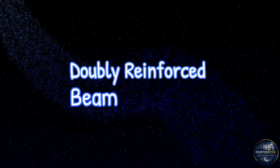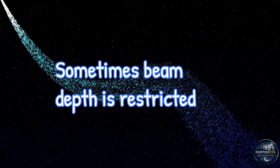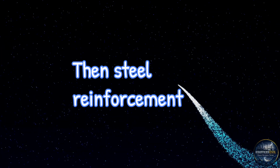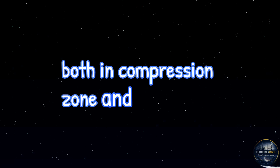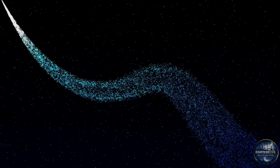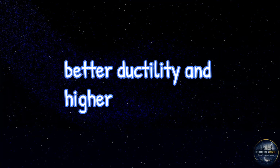Now doubly reinforced beam. Sometimes beam depth is restricted or moment reversal occurs. Then steel reinforcement is provided both in compression zone and tension zone. Such beam is called doubly reinforced beam. Doubly reinforced beams provide greater stiffness, better ductility, and higher moment capacity.